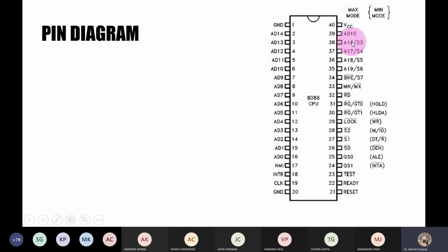But we have also seen that A16 to A19, these pins also have two meanings. They give status signals and address signals, and they are also bidirectional. So instead of 2 bytes, you will have something more, not exactly 3 bytes, but not less than 2 bytes. Since chips are available in the form of 8 bits or 1 byte only, 3 additional memory chips have to be used externally, so that the complete address from A0 to A19 is latched in the first clock cycle, the first tick of the clock, of every instruction.